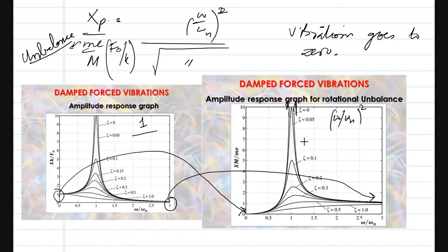So what I am showing you is one application in which you apply the concept of forced vibration, and what we identified is what the force equals, which is because of the unbalance, equal to m e omega squared. So you see, if you put e equal to 0, which means your center of mass becomes the center of rotation, then F goes to 0. When F goes to 0, there will be no vibrations. So the only way of reducing the unbalanced vibration is to balance the rotating body so that e goes to 0. This is the main idea.